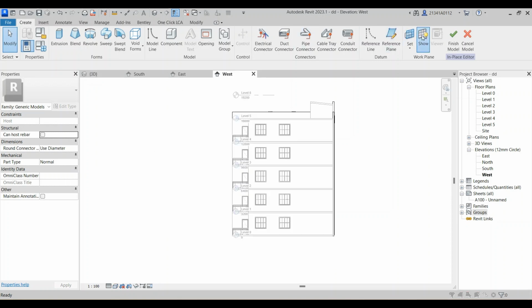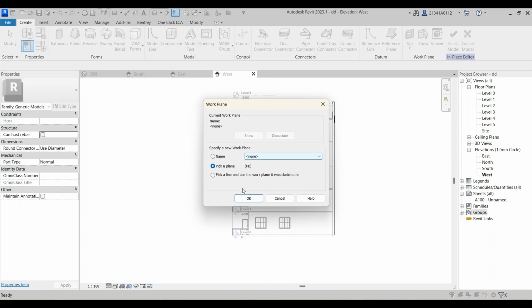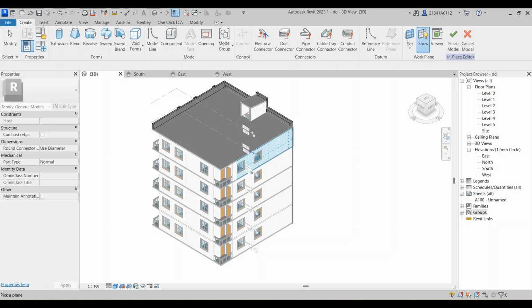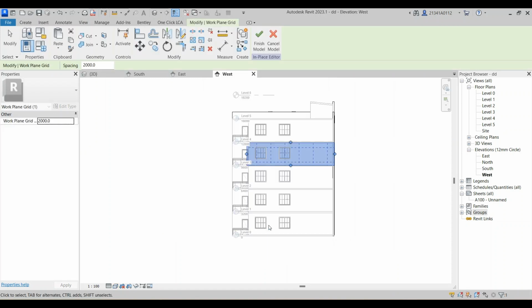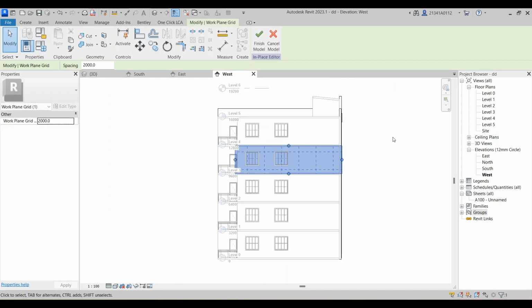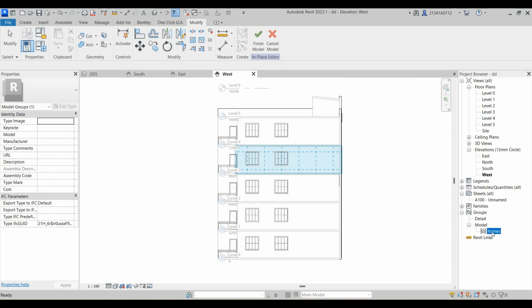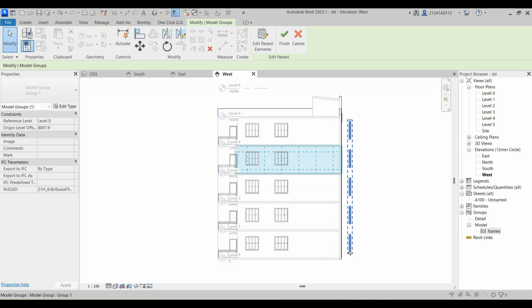Now create the exterior on the other side of the model. Again set a plane and pick a plane. Select the view to work on that plane. After that we can use the group we created. The group is saved in the project browser. Now we can access that group easily. Now we can drag the group into that model and place it down at your recommendation.